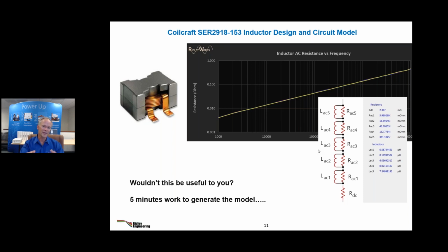But yeah, we're curve fitting a fifth order network to a complex curve. And sometimes it can do unusual things. So it's not always predictive of how the inductor is going to drop with each one on each stage. If it's a very lossy inductor, it's very predictable and makes a lot of sense. But as the efficiencies go up, it does things that will surprise you.